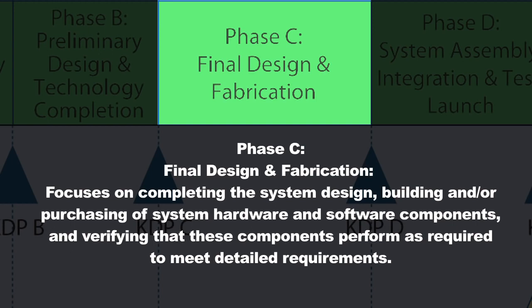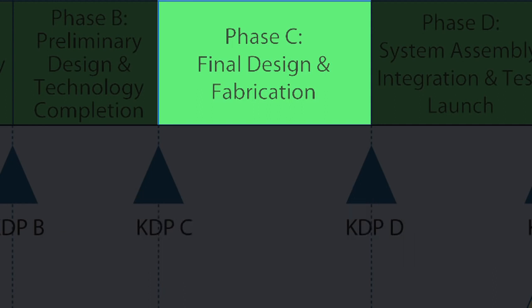And the other thing is, remember, this thruster has to plug on to the system, and so it might have to interact with the power system. It has to interact with the rest of the propulsion system, and those interfaces were defined in requirements. And again, you want to make sure that this thruster you purchased will be able to meet all those interface requirements. Now, again, in this phase, you're not actually building up the satellite yet. You're just procuring the individual components and making sure that they meet their requirements. The actual building of the satellite will come a little bit later, but at this point, your verification is all being done at the component level.